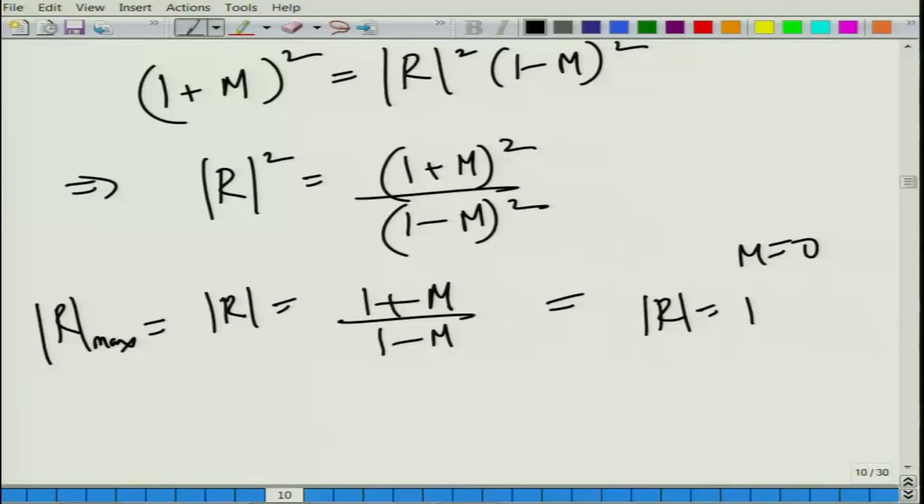However, when you have a non-zero mean flow, that is M is non-zero, it can be some number. Typically in exhaust pipes the maximum is 0.3, and 0.3 is really on the higher side. Typically it is about 0.15 to 0.2, and once it goes into the chamber because of expansion it is even smaller, although we would not really allow it to expand due to a number of reasons which we will discuss in this week's lecture.